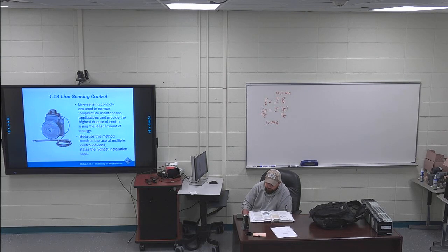123. In the second paragraph, I've got the first 3 sentences highlighted, keying in on the last one. A PASC, proportional ambient sensing control, uses a programmable electronic controller connected to remote temperature input modules and contactor control modules to regulate one or more heat tracing cables. The PASC system monitors the ambient temperature and operates to continuously adjust the heat input to compensate for heat loss that occurs during the changing ambient temperature conditions.